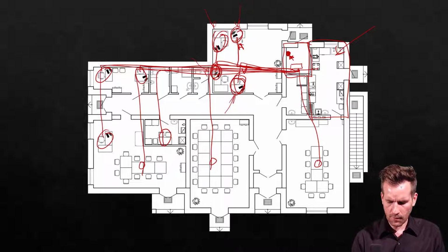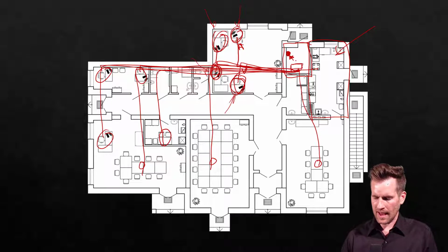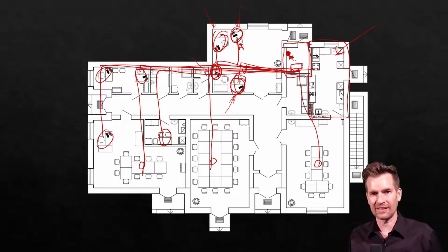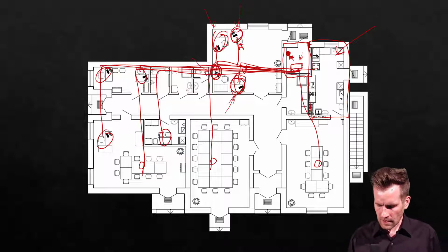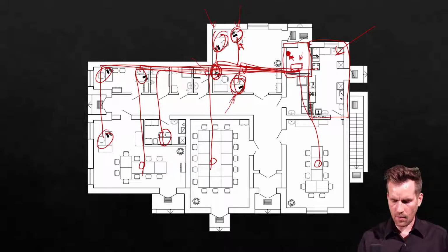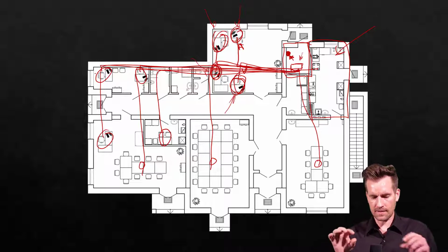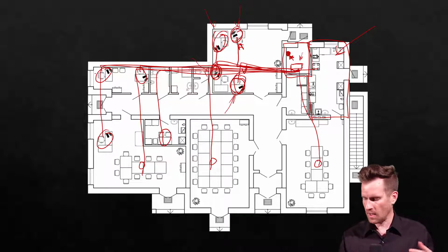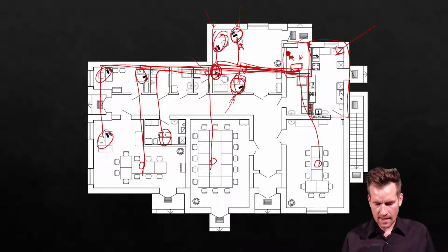So you get the point: I'm going to run all my cables from this single location, and I'm going to what's called home run this all out to these different devices, and they're all going to come into this rack right here. On the end here, what I'll probably do is I'll have jacks in the wall, and there are these little jacks that you punch down and plug into the wall. So I'll put those all into the wall, so that way these devices can connect.